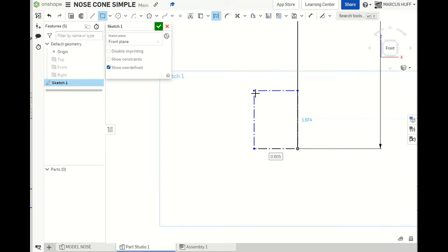We may need to refine this a little bit as we print, but I found that about 0.93 inches is our target value for the cone. So we're going to put 0.93 divided by 2 because 0.93 is our diameter, and we need to divide that by 2 for the radius. And then this depth is going to be 0.8 is good. So what this is deciding is how deep it goes into the rocket, and this is deciding the diameter, okay?